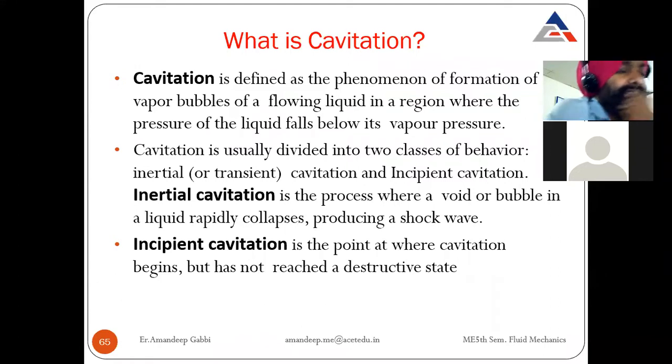Now, there is a term cavitation. If you understand what vapor pressure is, cavitation is a phenomenon that occurs wherever there is a fall of pressure, and pressure falls below vapor pressure.